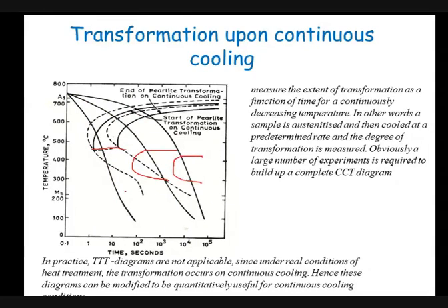By adding alloying elements, you get one more bay, which we call the bainitic bay, and from there you can cool it and get bainite. But only certain alloying elements give a separate bainitic bay, and only in some types of steels, not all steels. In some steels this bainitic bay exists and you may get bainite, but it's very difficult.